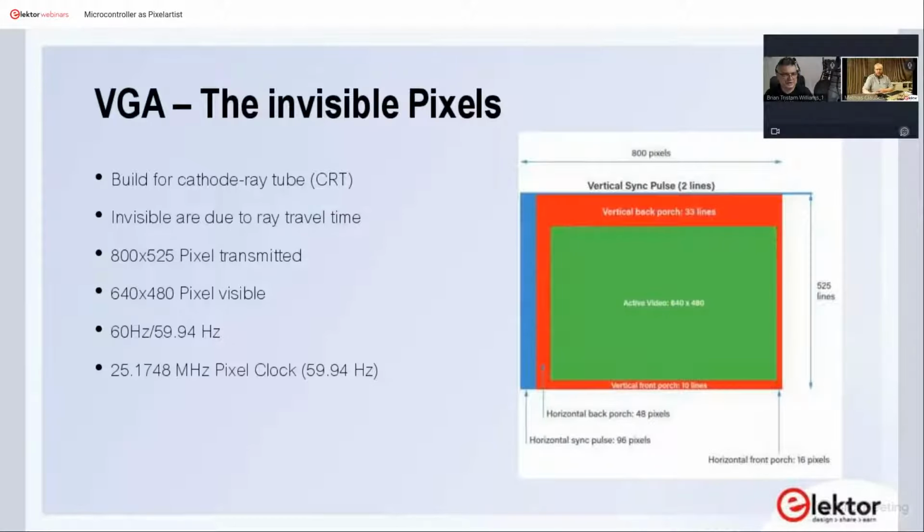It's interesting that they chose the 525 line standard like NTSC, even though it's not interlaced, so it uses a lot more bandwidth. Yes, but in the end, if you have an NTSC color tube, you can use the same tube with a lot less circuitry around it, simpler circuitry, and that's it. So it's basically a color TV without the TV logic, more or less directly driving the tube itself at a little bit higher frequency. But that's where it started. So you can see the TV standard followed us a long, long way.